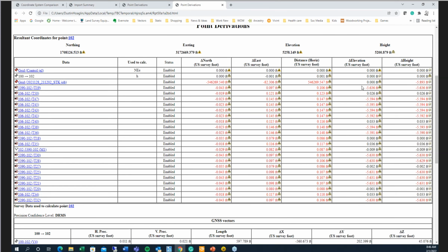So I can look at the biggest errors first and solve them. I can look at these and go, oh, this is probably prism constants or something, right? Most of these total station vectors are coming in from the east, and then obviously I have some rod height busts in here that are 5 feet off. So it's either a measure up on the height of the total station, or on the rod, looking at these vertical errors, right?